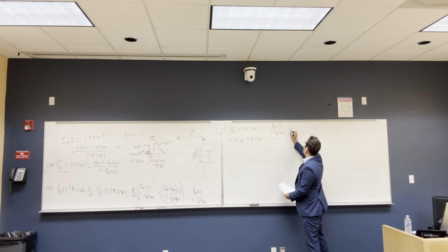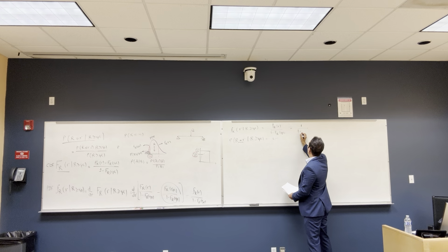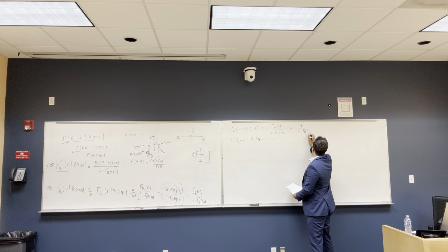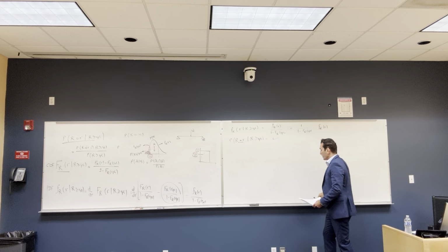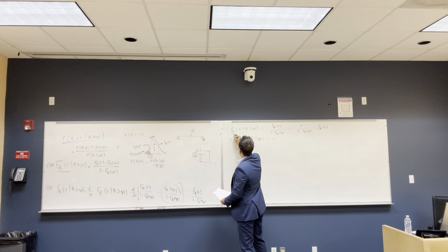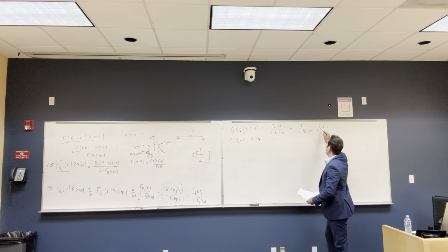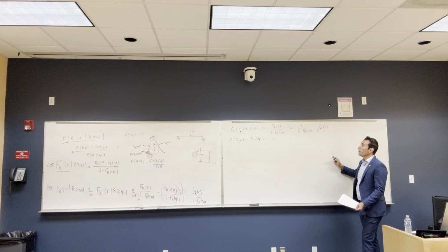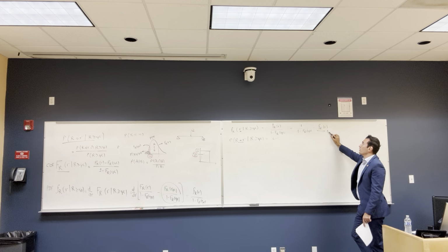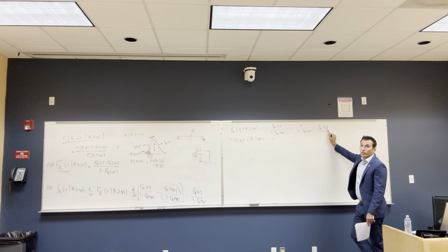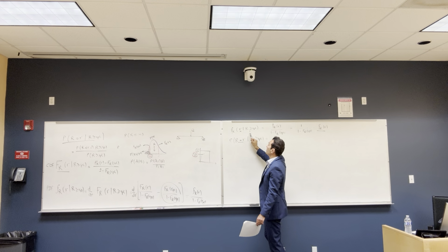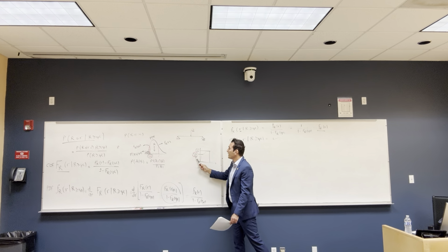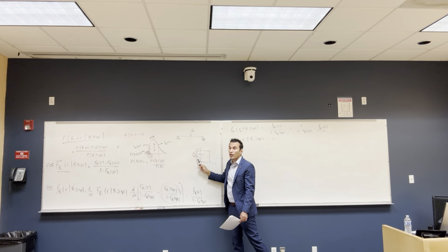So this finally is going to be equal to 1 over 1 minus F_R(R_BL) multiplied by, so what is this? By the way, this is F_R of R, and this is F_R of R, okay? What is the difference between them? This is F_R of R, not conditioned on anything. That is the probability of your random variable to be equal to the capacity. But this is the probability of your random variable dependent on already your capacity exceeding the yield load.